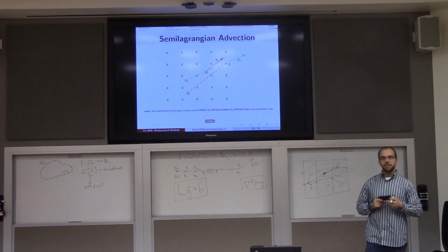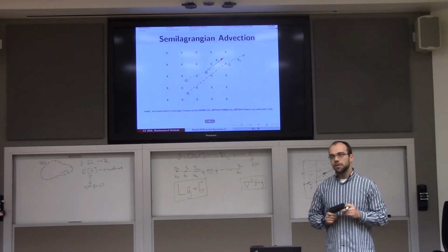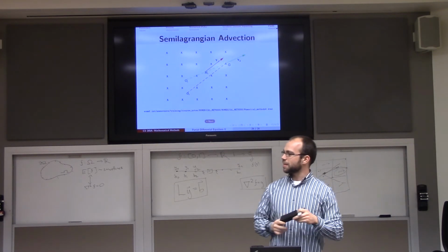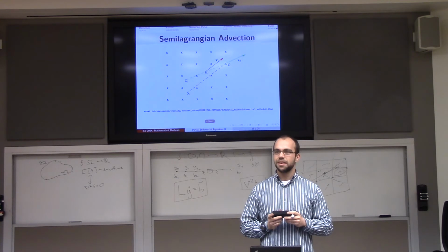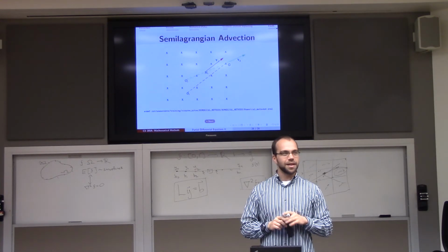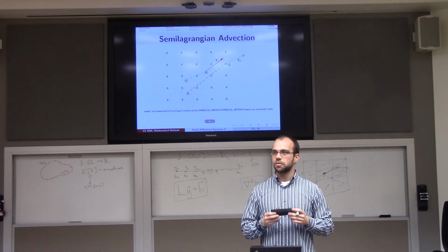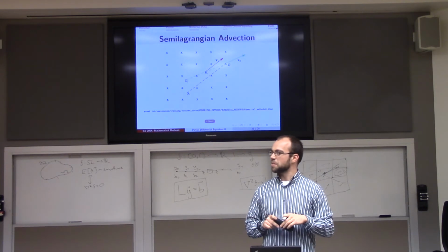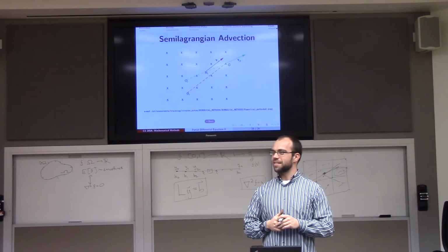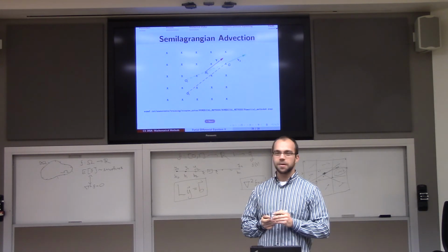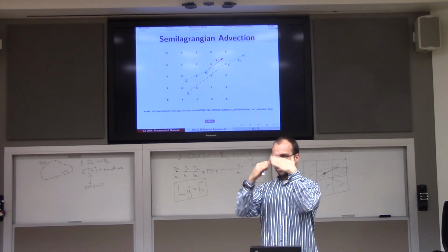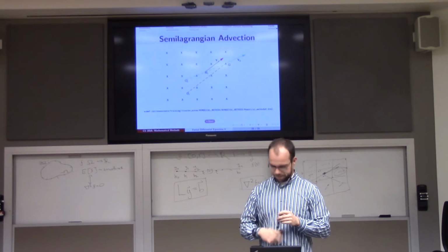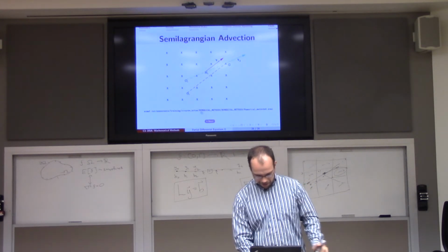So anyway, actually fluid simulation isn't so bad, right? You update your pressures using one of these elliptic solves, which is something we've covered in detail here. And then you advect velocities and you advect densities and you repeat. Obviously it gets much more complicated when your fluid has a surface, for example. So simulating smoke, I think, is generally a little bit easier than doing water, where it's splashing around under surface tension and so on. Right. So anyway, that's all we'll say about that.